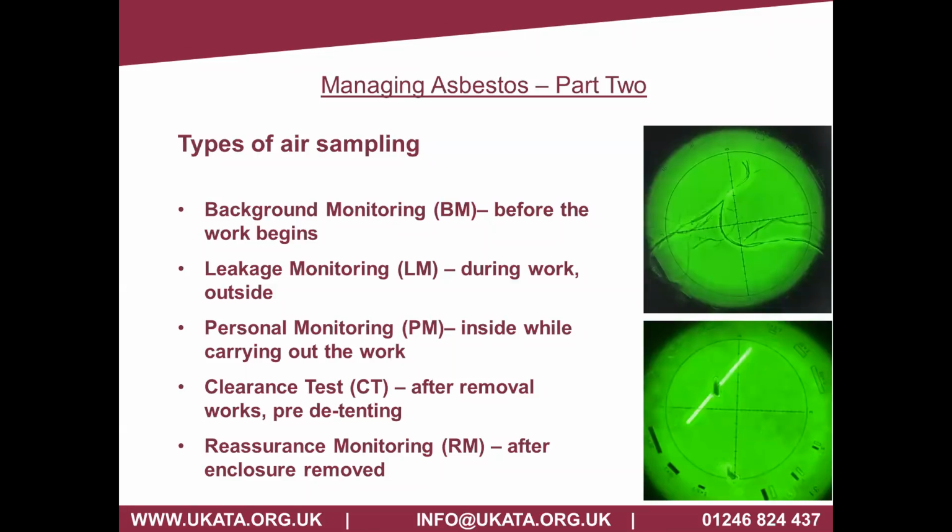The clearance test, this is done after the removal works, but done inside the area to determine the level of exposure or level of fibre concentration inside the enclosure prior to them removing the enclosure. And then once obviously the removal works has been undertaken, the enclosure has been taken down, an analyst could obviously also undertake some reassurance monitoring after it's removed.